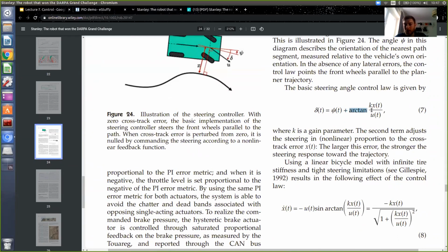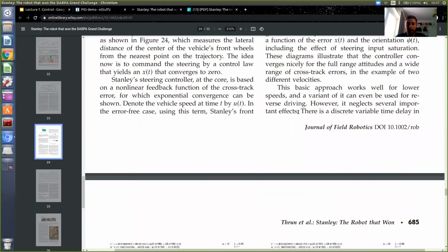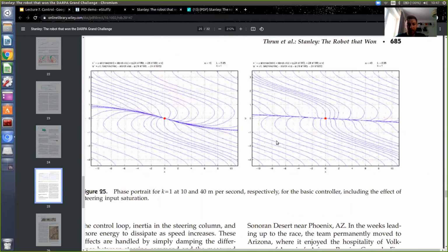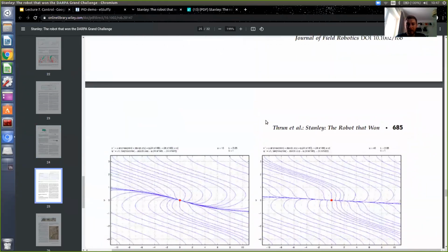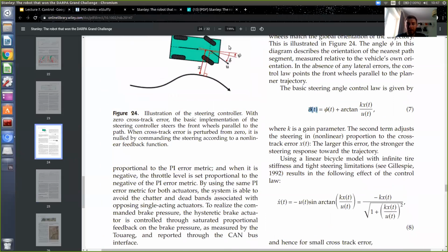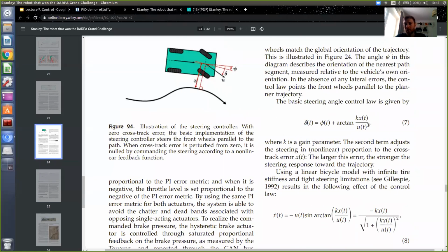And our arctangent here is just to switch from some numbers to angles, obviously from -pi to pi, because in the end we want to get the steering angle of our wheels. So we need to work with angles in the end. And there is some justification that this control algorithm is working. They prove that this control algorithm is stable. It will never lead to instability in the system. You remember that instability is when we, for example, oscillate our steering wheel. So there is a mathematical proof, but the whole algorithm is really simple.